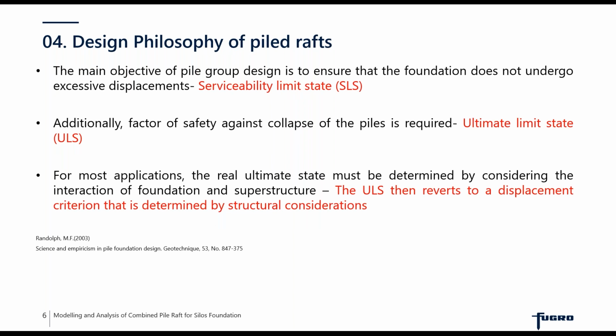Now, when it comes to the design philosophy of the pile raft foundation, it is also governed by the serviceability and the ultimate criteria. The main objective of the serviceability criteria is to ensure that the foundation does not undergo excessive displacement, and the ultimate state criteria is to provide a sufficient factor of safety against the collapse of the pile.